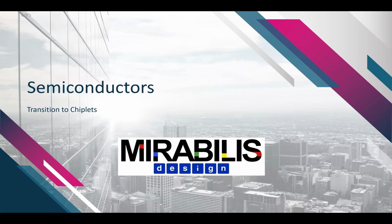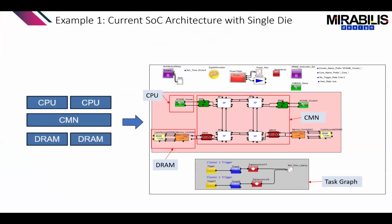and then evaluate if this combination works for this particular application or use case. When we look at chiplets, let's take an example where we had a current SoC architecture with a single die. You can see how they're all connected, how the CPUs are connected. We have the DRAMs for this set, and DRAMs here for this set. And of course, we have the task graph or the workload.